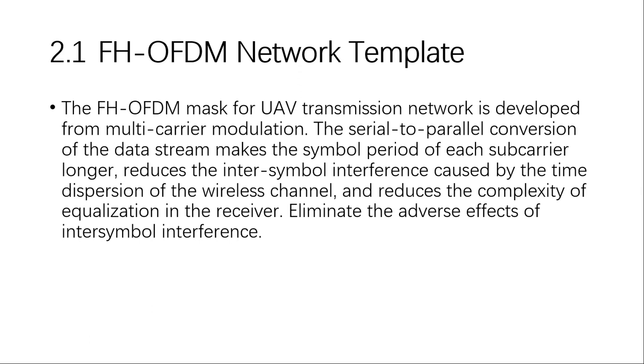The serial to parallel conversion of data stream makes the symbol period of each subcarrier longer, reduces the inter-symbol interference caused by the time dispersion of the wireless channel, and reduces the complexity of equalization in the receiver. It eliminates the adverse effect of inter-symbol interference.